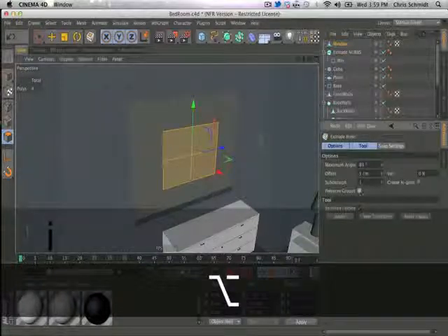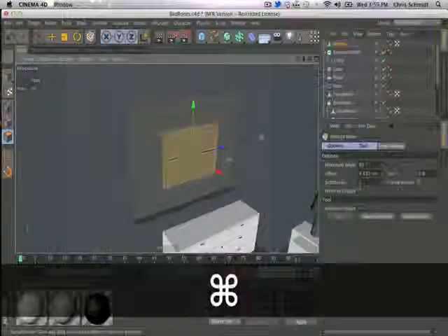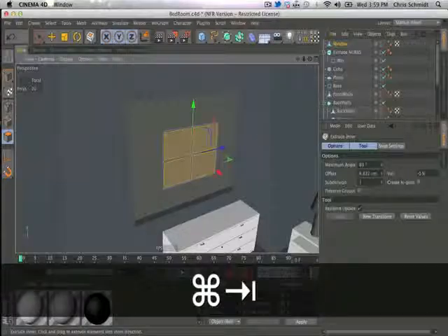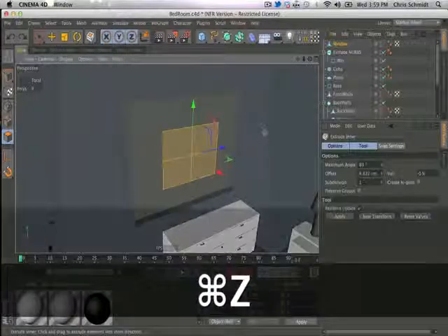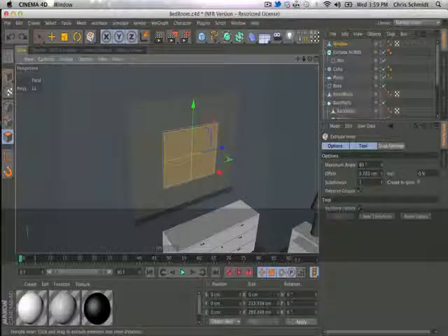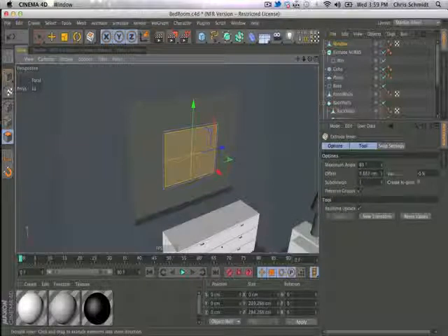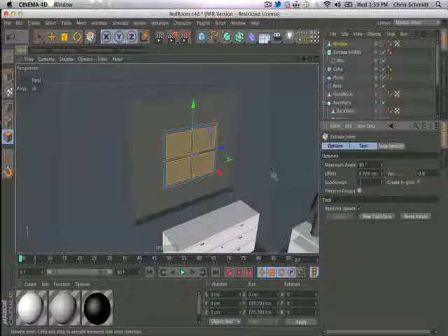Hit the letter I, turn off preserve groups. Do a little inner extrude. Those are pretty thin. Actually, it looks like there's supposed to be a little perimeter, so I'm going to hit preserve first, same as with our cabinet. Now we're going to do a second one, and the second one won't be preserved. And now we can make that maybe not so thick, so nice and thin. And then we can just hit delete.